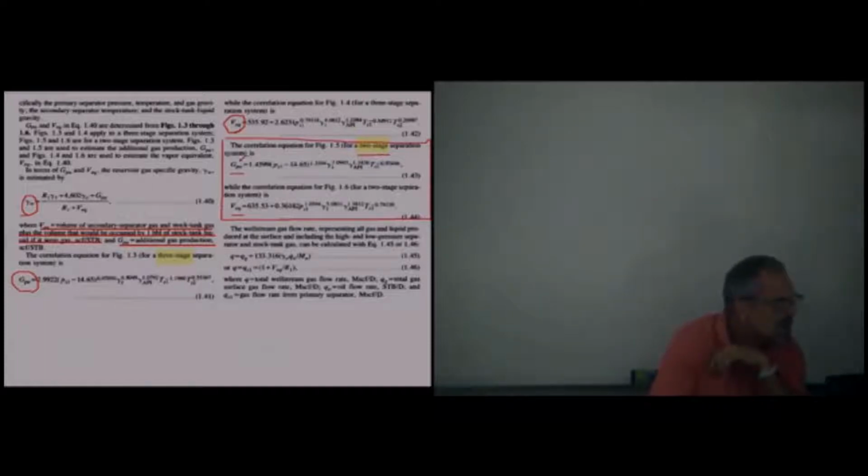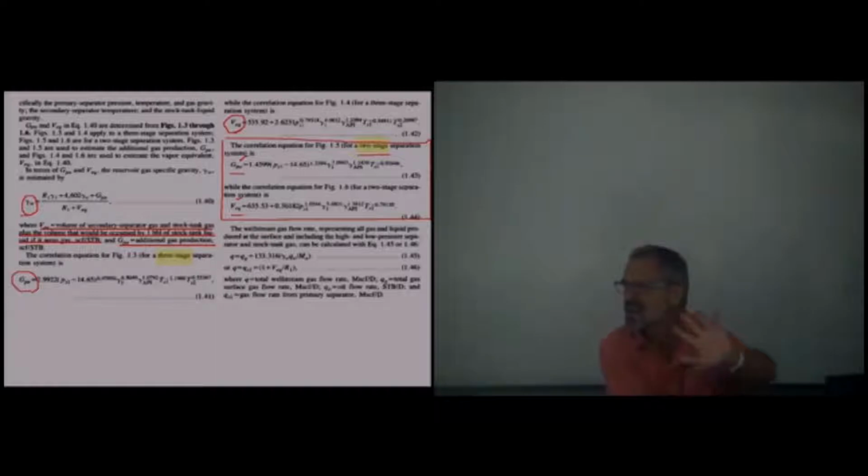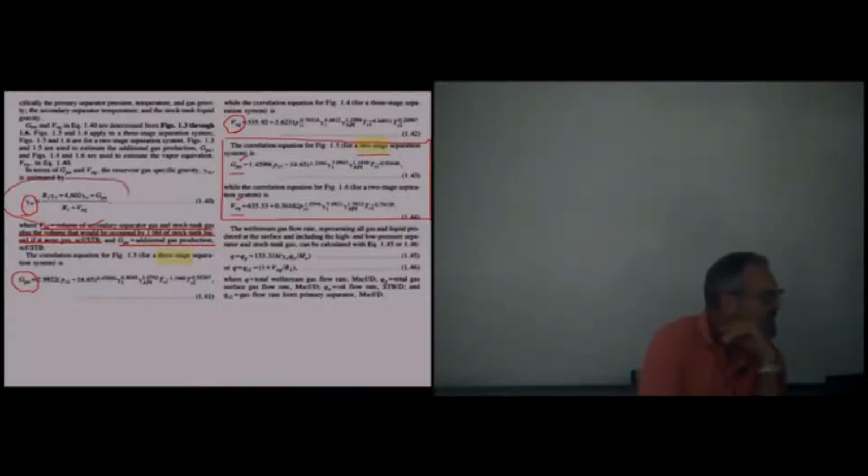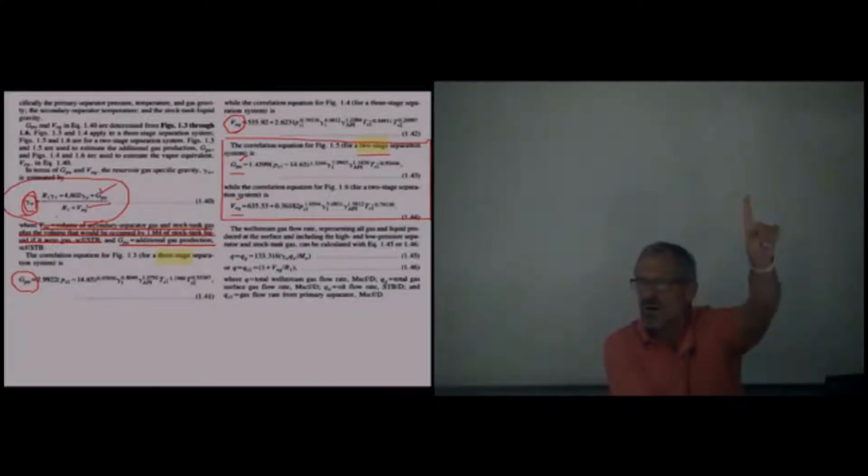We're going to subcalculate a GPA. We're going to subcalculate a VEQ. We're not even going to see what they are. I don't even care what they are. But we're going to utilize this equation that uses GPA and VEQ, and we're going to calculate the well stream gas gravity from one GOR, R1. The gas we sell from the separator compared to the oil we sell from the stock tank. By and large, that's the only number I usually have.